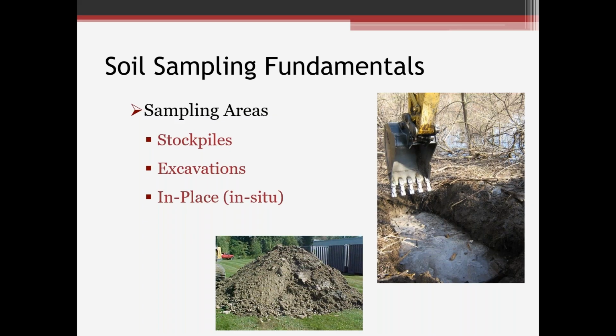So a little bit more in depth with trying to get that done. You could also do some test pits for in place, but you've got to weigh the benefits and consequences of doing some pretty destructive sampling versus a little bit extra there, and having minimal disturbance to the site before we do anything further. So some different things come into play depending on the sampling area.